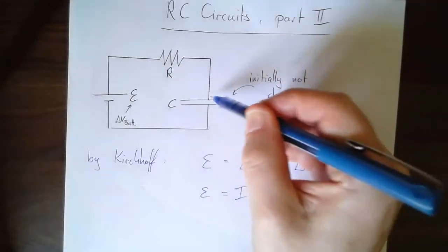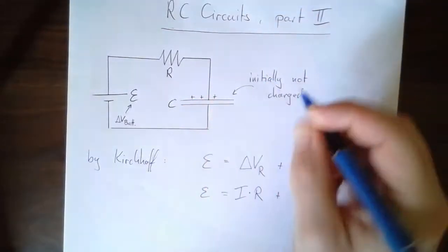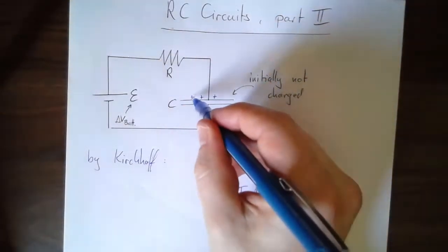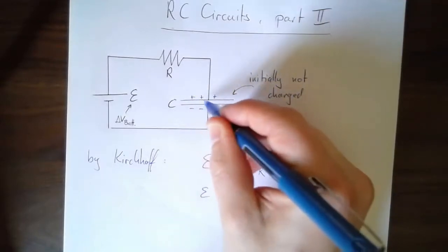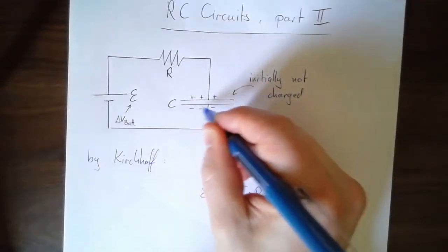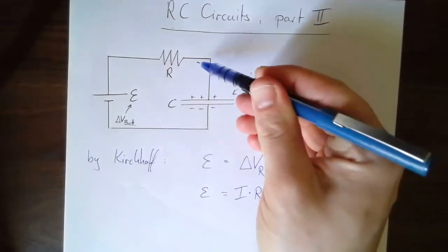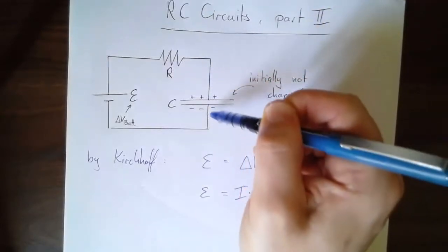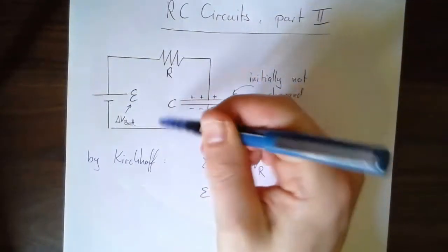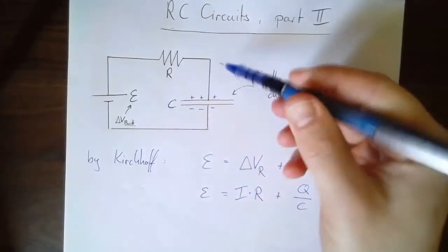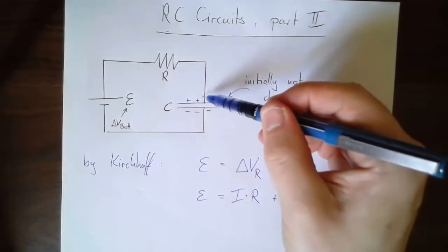We're going to get pluses on this side. I guess I'm going to add them now. Just that initially it's not charged. Those pluses, they're going to make minuses appear here because they get attracted. They come to the wire. They build up here. So the effect is that if they arrive, like pluses, if they were moving, would be arriving here and leaving on the other side. So the current is flowing all the way around. It's bridging the gap, even though no actual charges are jumping.